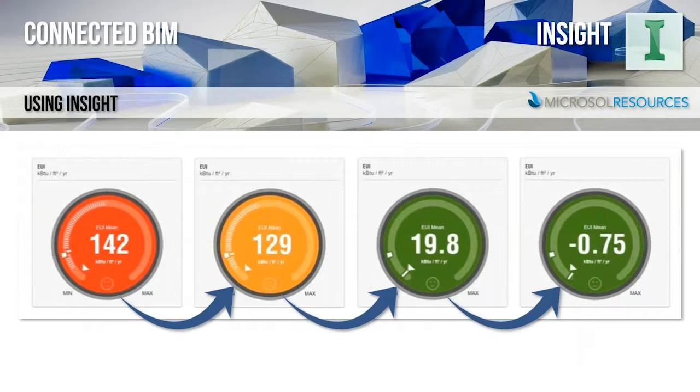So back on the topic of the energy cost mean a little bit. It can either be cost or EUI. It's often easier for users to see the energy cost mean represented in dollars per square foot as opposed to the EUI. I'd recommend using cost, even though the 2030 references EUI, as you get started. If you're unfamiliar with EUI, it's a building's annual energy use per unit area, and it's typically measured in thousands of BTU per square foot per year. It's important as EUI is useful for comparing performance of buildings across sizes, types, and locations, and used in a number of different reporting.